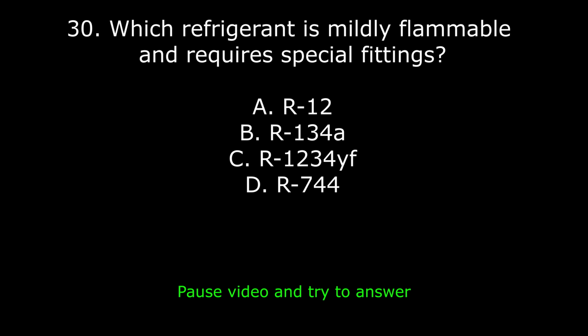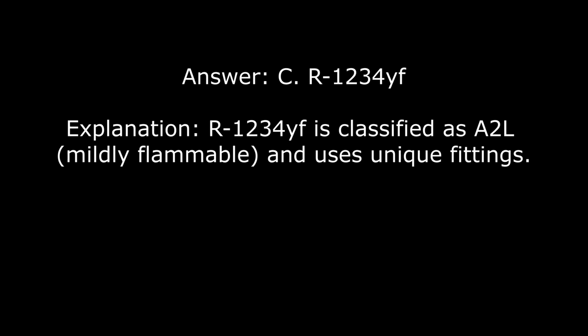30. Which refrigerant is mildly flammable and requires special fittings? A. R12. B. R134a. C. R1234yf. D. R744. Answer: C. R1234yf. Explanation: R1234yf is classified as A2L, or mildly flammable, and uses unique fittings.